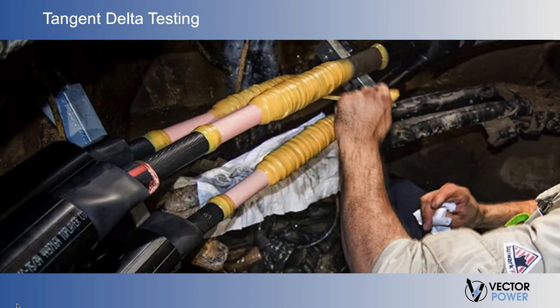Now, it should also be noted that in the event the cable circuit has transitions between multiple insulation types, for example, cross-linked polyethylene transitioning into EPR, the tan delta value will be influenced by the component with the higher dielectric losses.